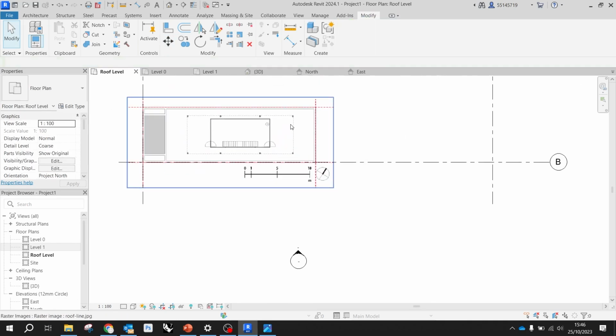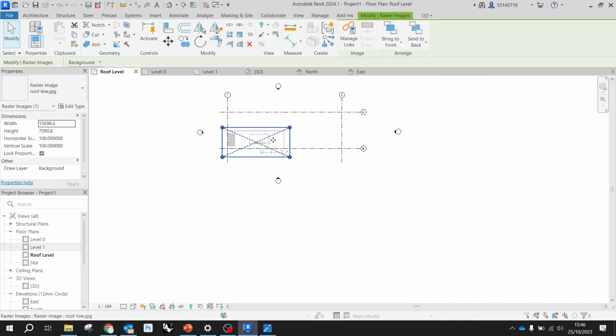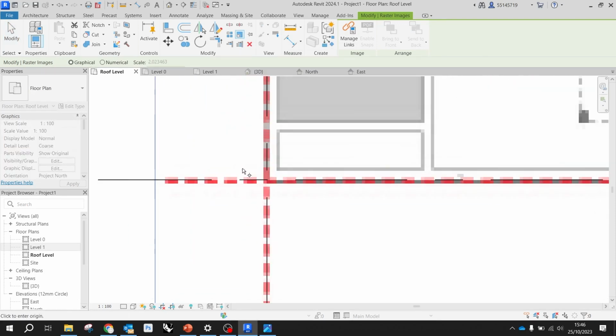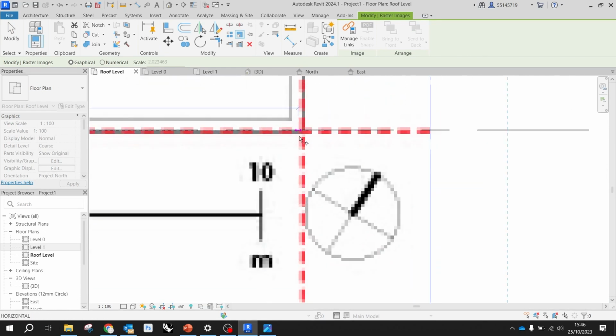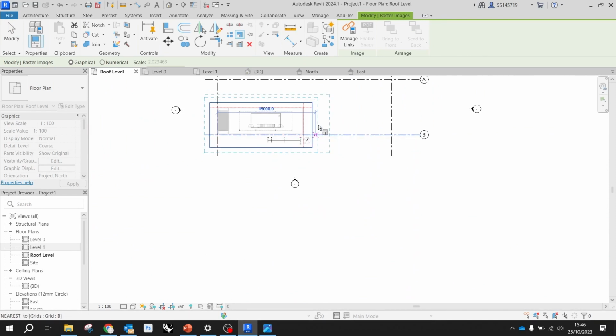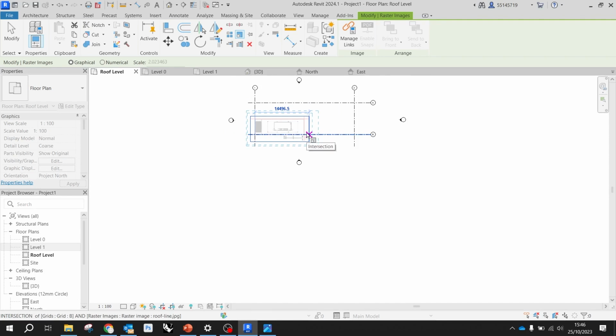Second thing that we need to think about is getting this back to scale once again, right? So first selecting the image always, I'm gonna get the scale command, pick again the first reference point, then the second reference point, which is gonna be the other red grid, and then I know that basically this dimension has to cover this full size.